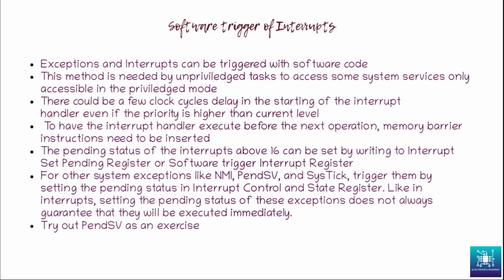When an interrupt is asserted, if there are instructions coming in the pipeline after the instruction where the interrupt occurred, there is a possibility that an instruction or two after the current instruction at which the interrupt has occurred gets executed. To prevent that from happening, say we don't want any other instruction to be executed once the interrupt comes in, we will clear the pipeline.